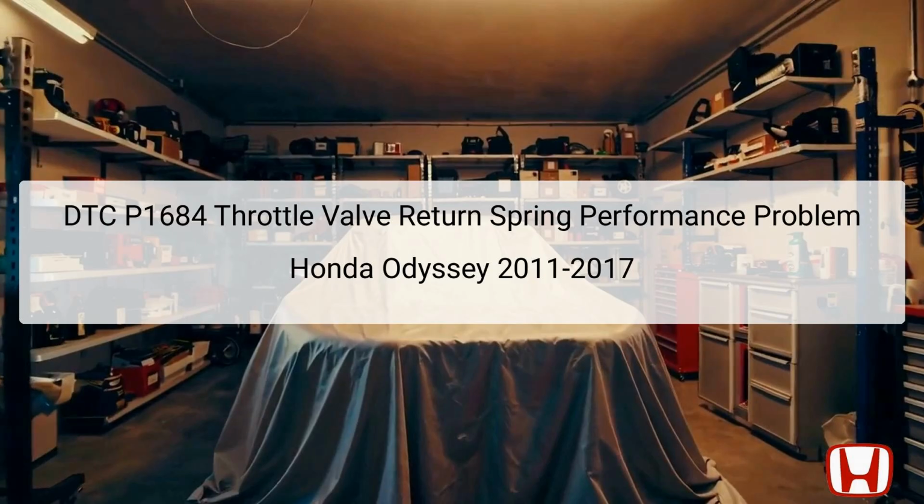optimal air intake. However, if the return spring malfunctions, it can cause the throttle valve to stick or be sluggish in its response. This can lead to poor engine performance, increased emissions, and potentially safety concerns if the vehicle does not respond appropriately to accelerator input. It is critical to address this issue promptly to ensure safe and efficient vehicle operation.